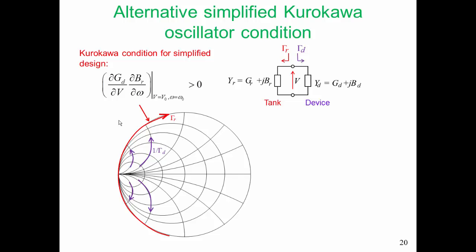in the resonator network. That previous interpretation could be used with either a VCO with finite loss in the resonator network, or it could be used with a fixed frequency oscillator. But this interpretation shown on this slide cannot be used with a resonator that has significant loss. Or I should say you could use it, but you'd find design to be very difficult because the intersection is going to appear on one of these curves here. So if there's finite loss, we're going to follow one of these curves. And our intersection is going to occur in this region here.